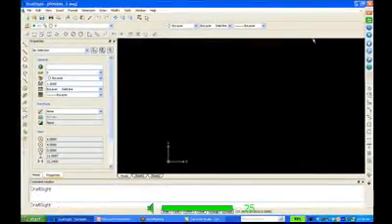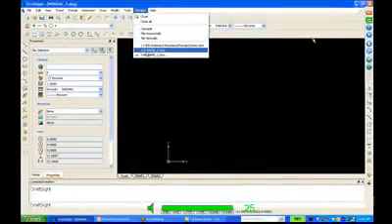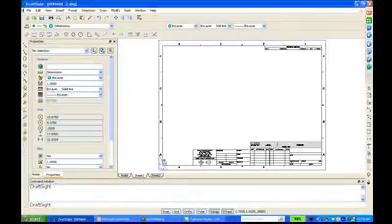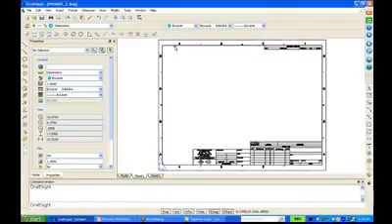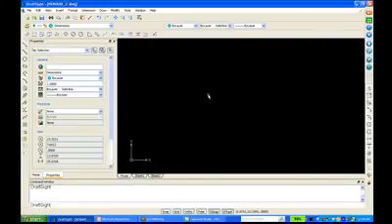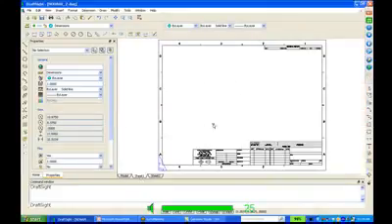We did have a question. The question was how to bring the template file into the paper space. I call them sheet space rather than paper space. So what I'll do is put it on sheet 2 because I did something to sheet 1. When I'm using DraftSight, my work is done typically in the model window. And what I like to do is put my drawing border itself in the sheet window. This way it doesn't go onto the model, but when I go to print, I print from the sheet and I can get the drawing border to print with it.